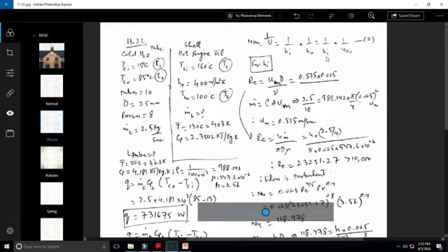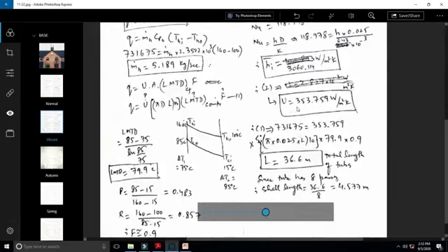So we will then put this H of 3060 over here. It would be 1 over 3060 plus 1 over 400, and we would be able to get the value of the overall heat transfer coefficient using equation number 2. So we get it as 353.7 watts per meter square Kelvin. The units of U would be the same as that of H.